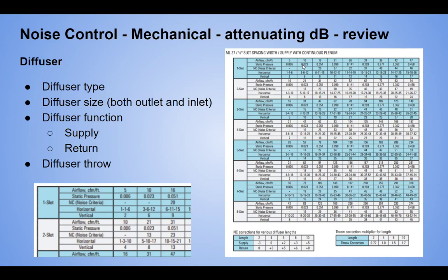That's why it's just better in performing arts. You just kind of open it up, slow down the air, and let it fall from the ceiling is the best option. Not getting a lot of turbulence air on there. It's harder to do though because you're not getting that throw on there. And that's the basics. That's the basics of background noise from a mechanical standpoint.